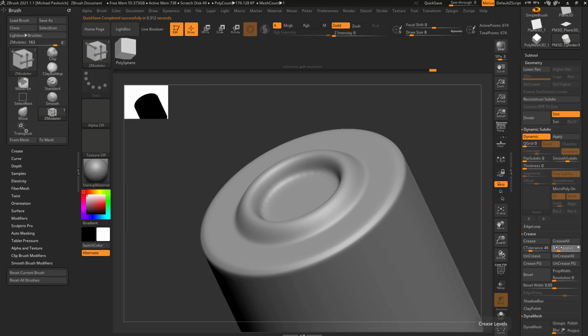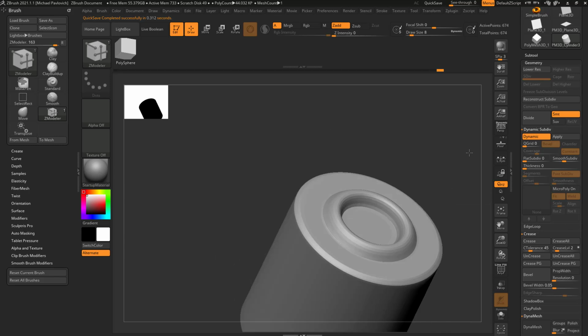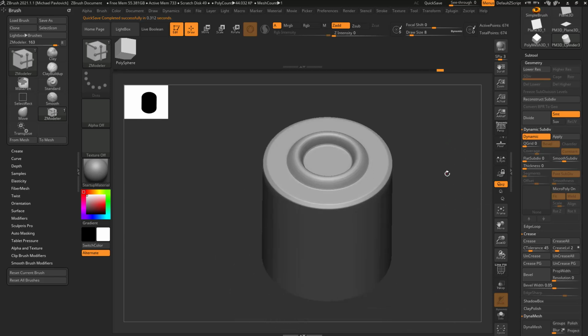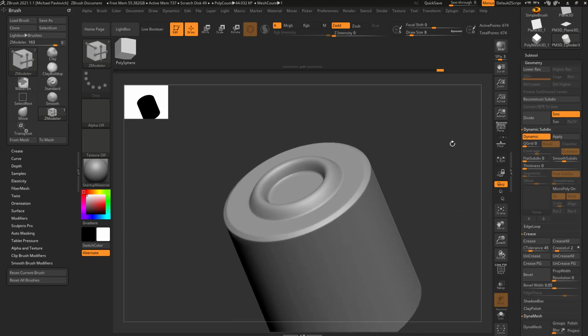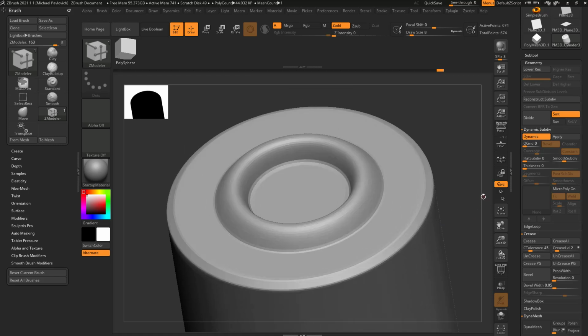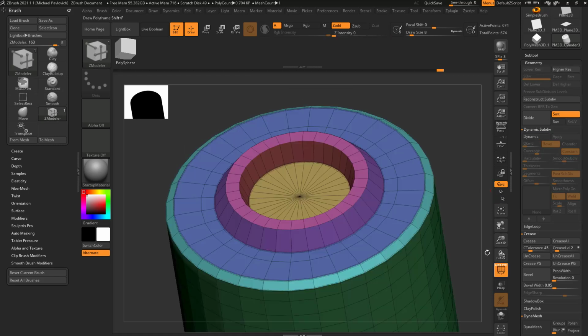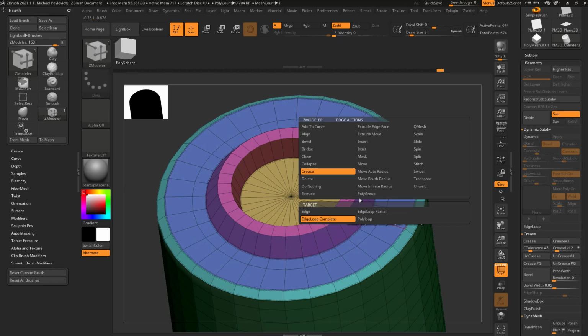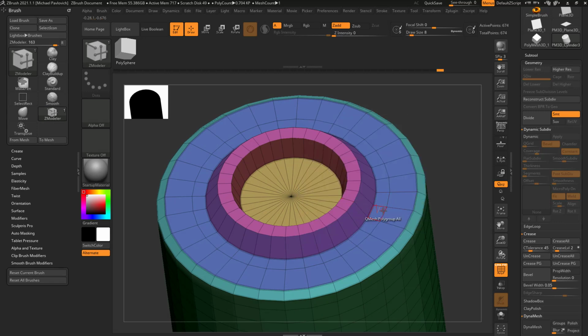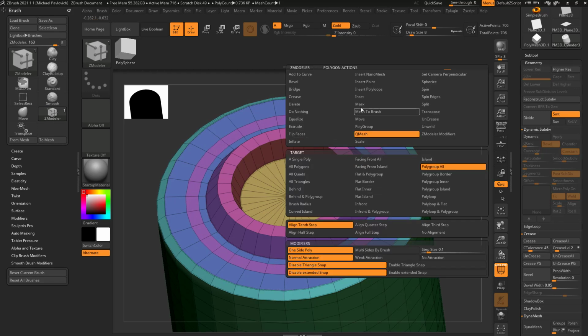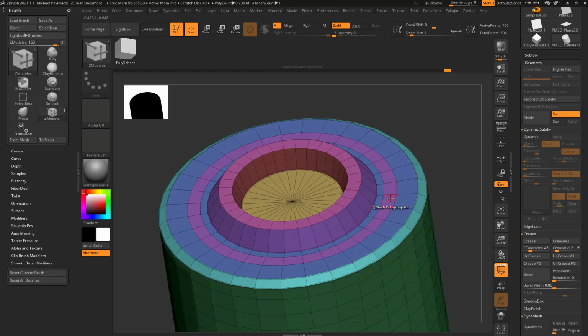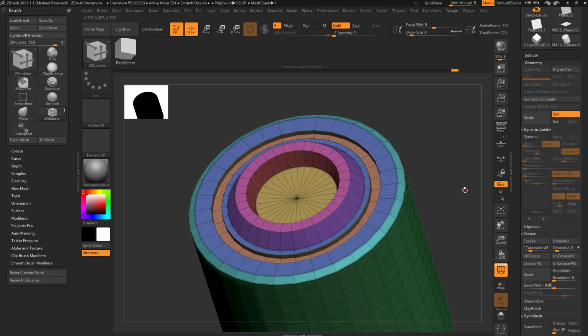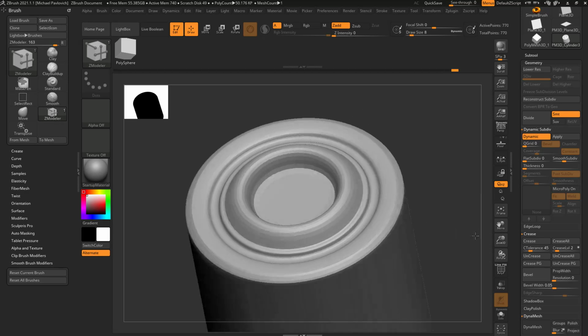Generally speaking, I'll do like a crease level of 2, smooth subdiv of 3, and that'll kind of be my working resolution as I'm previewing things. And again, the cool thing about not having real subdivision levels is I can always do Shift D, and I can continue to come in here and keep modeling. If I want to say, bevel, edge loop complete through here, and then say QMesh, polygroup all, and push this in. I can hit D for dynamic subdivision, and then I'm back in here.